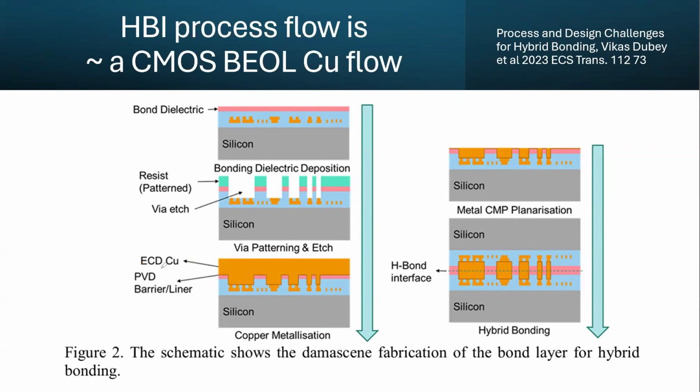electroplating, copper ECD. This is the name of the tool, from Novellus. Copper tools are plating tools. These are plating. And then the liners are PVD liners. They are not going to CVD or ALD yet, still in the PVD area. All these are the dual-damascene process.